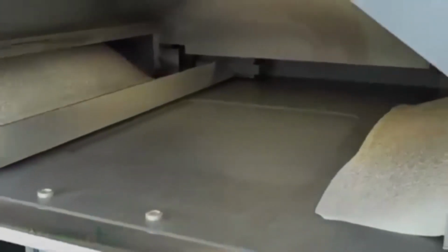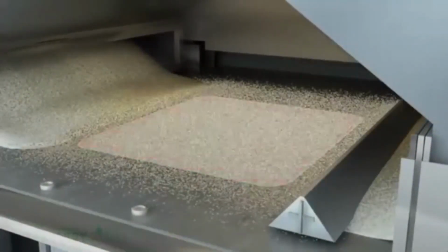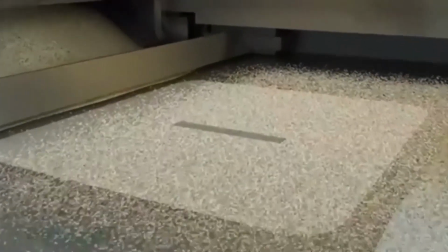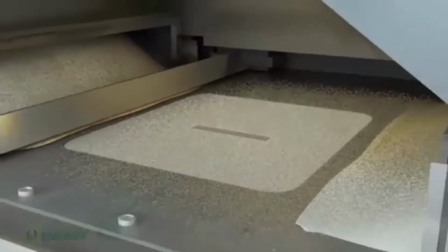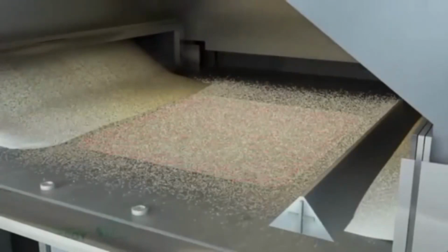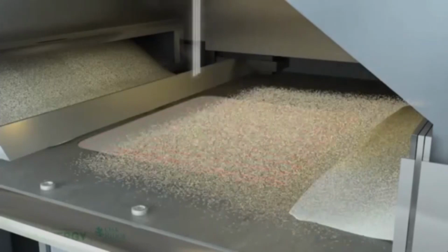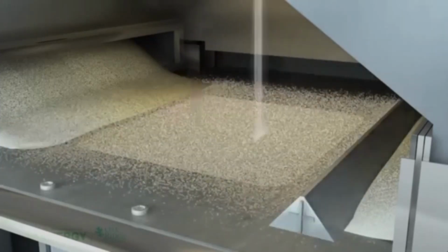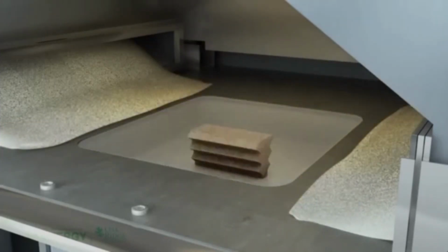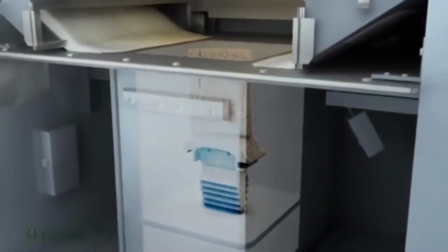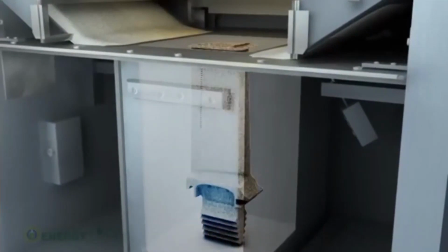The powder particles available here now can be deposited onto the bed, and then the powder gets melted wherever the beam falls onto it. Of course, before the melting, a preheating operation occurs that you can see here in the red color light. So that is showing the entire bed is getting preheated and then the required region is getting melted. So preheating and melting are the two subsequent operations used to occur for each layer, and the entire part is built like this.